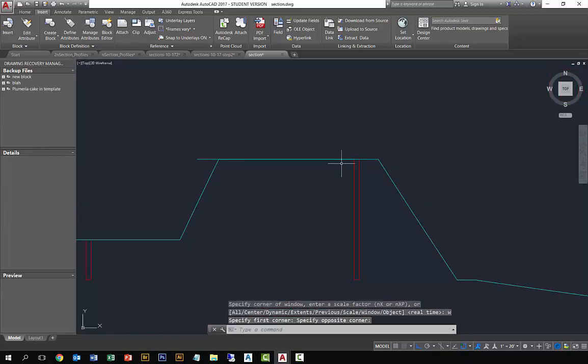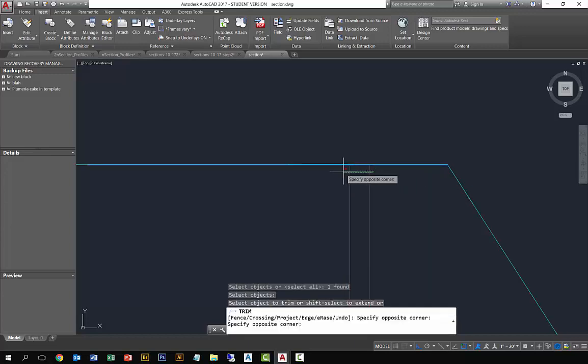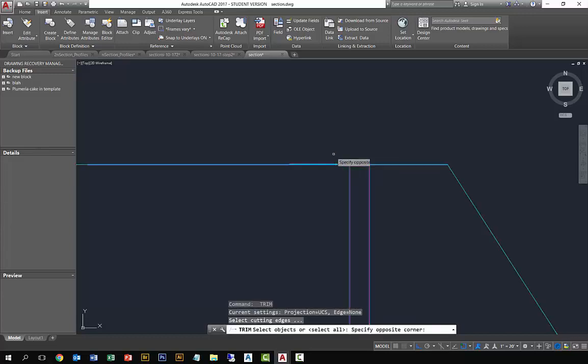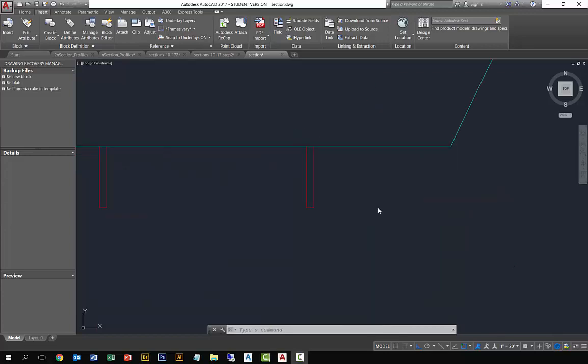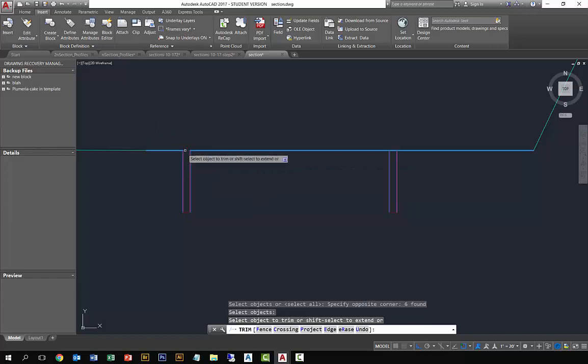everything should be fine. Now you notice I've got information on top of one another, so I've got to delete some of this extraneous data that your instructor seemed to have left in her file. So file hygiene, important. At the end, to bring to the laser cutter or the knife cutter, this same process can apply to either. You need to bring a series of 10 closed polylines on a single layer at the correct model scale so that the knife cutter can follow your path.